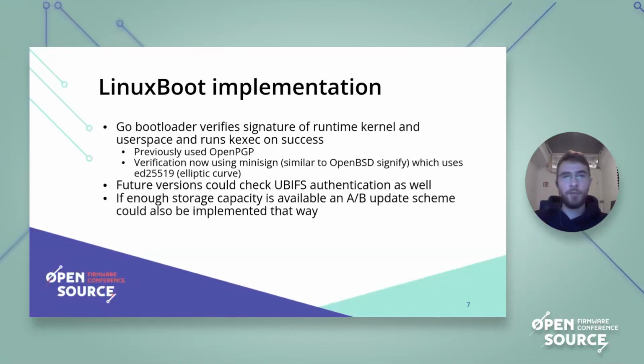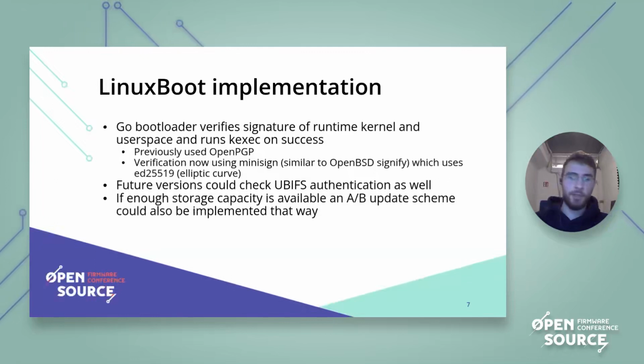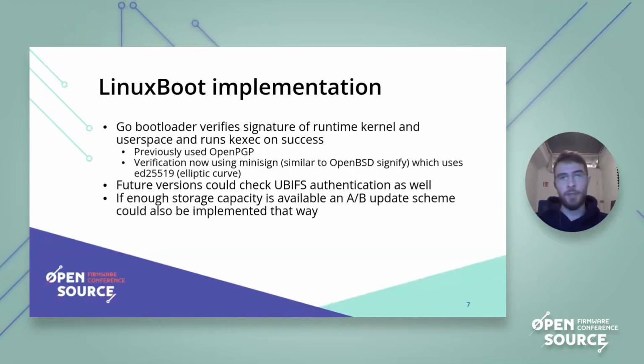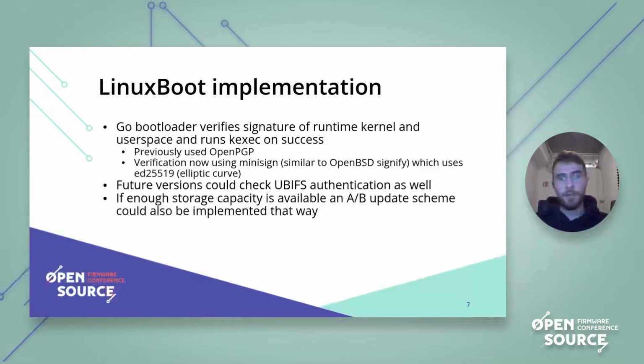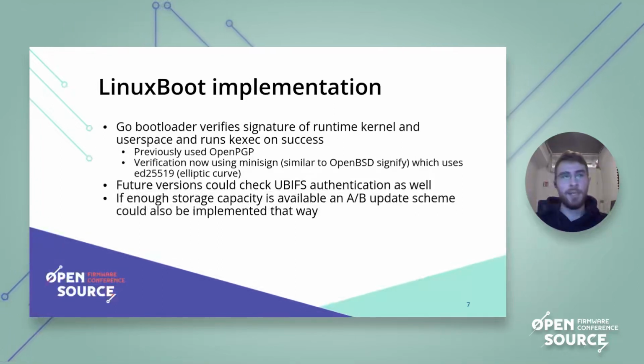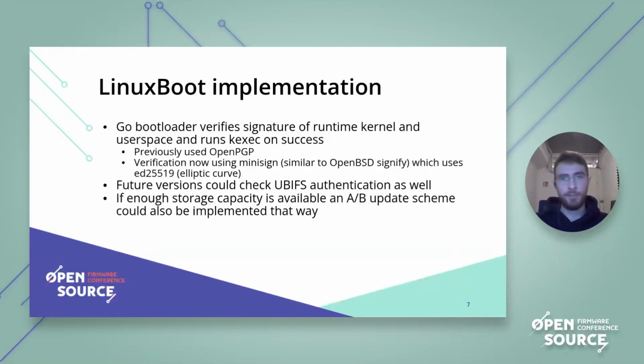So this way you can have graceful updates and don't need to worry that something that happened during an update could crash your whole stack, because you can always go back to the other partition. That, of course, requires a little bit of extra space and would only be available on more modern BMCs. But in this case, modern means anything past 2016 or so.